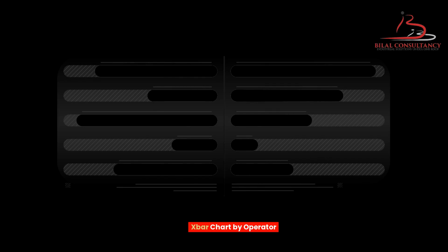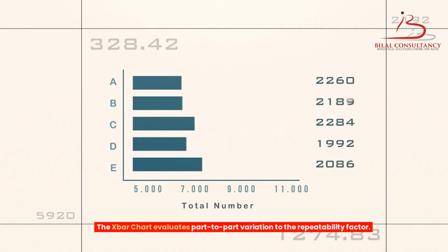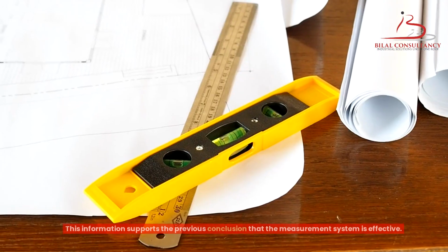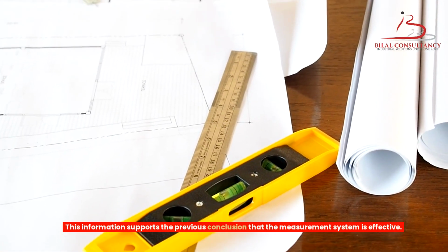X-bar chart by operator. The X-bar chart evaluates part-to-part variation to the repeatability factor. This graph indicates the patterns of the two appraisers are similar. This information supports the previous conclusion that the measurement system is effective.